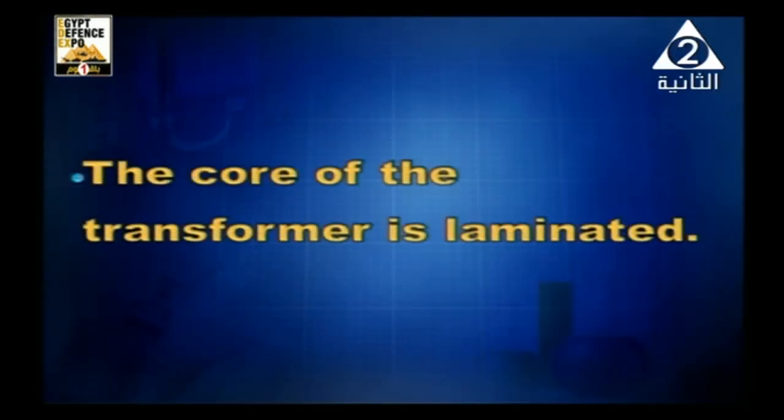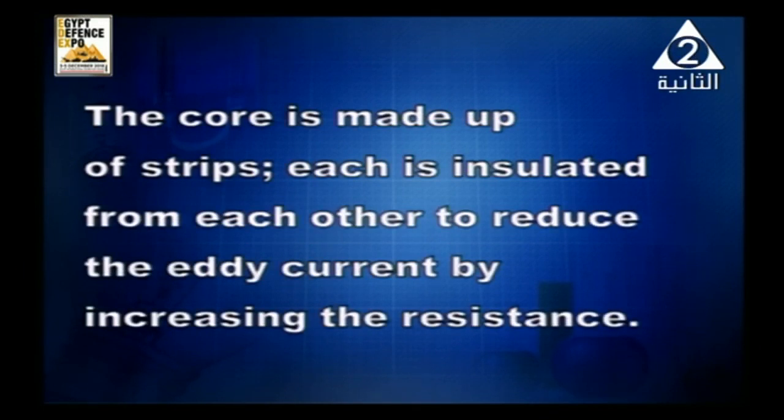Another give reason: the core of the transformer is laminated. The core is made up of strips, laminations. Why? Each is insulated from one another to reduce the eddy currents by increasing the resistance.